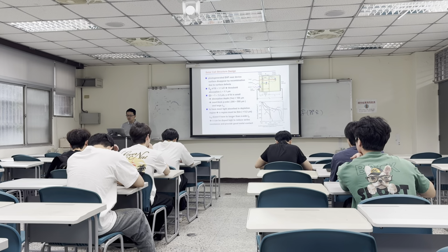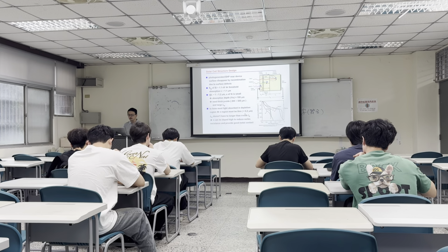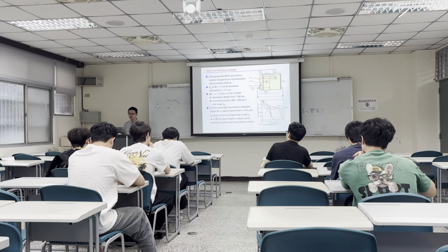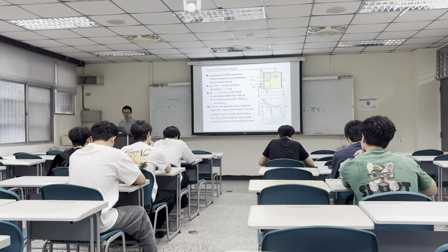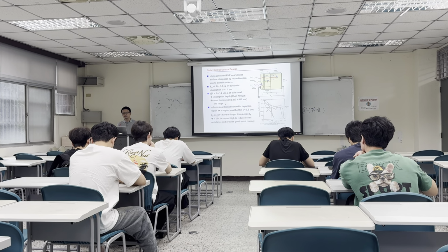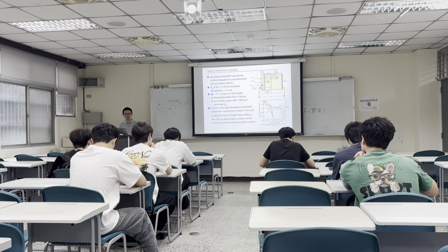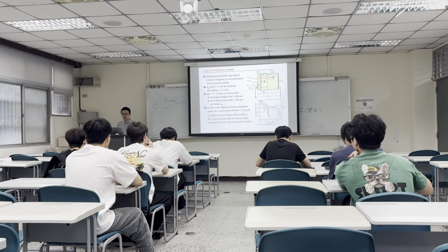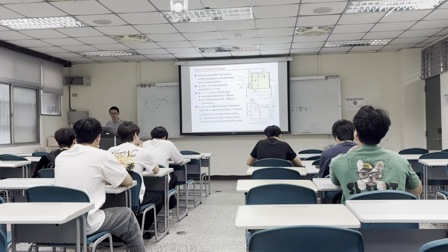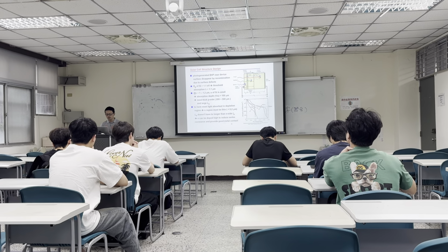And since we make this heavily doped, the hole diffusion length doesn't have to be long, because no matter what, the N plus region is only 200 nanometers, it's not that thick. So the region can be doped heavily to reduce the series resistance and provide a very good metal contact to lower the contact resistance.